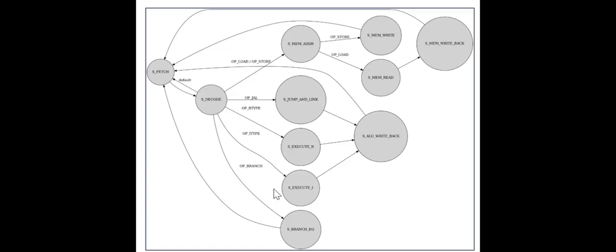This is assertion lab SVA, immediate assertions. Here in this design, we have a typical RISC-V FSM. It goes to the fetch, decode, and then execute cycles, or states. And we want to add a couple of assertions to check the right behavior.